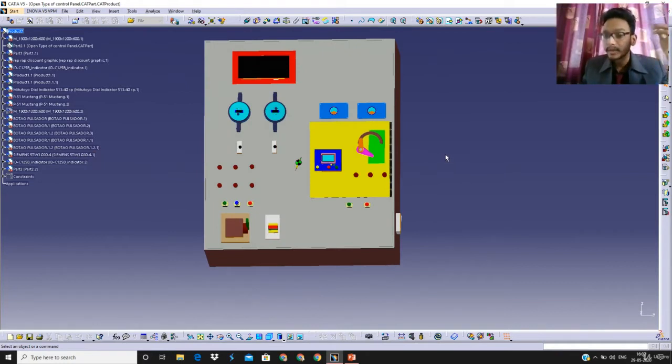And at the left side you can see there is a starter of a 3-phase induction motor. Before going to deal with this procedure, you have to use these contactors 1 2 3 4 5 6. So we are using 6 contactors to deal with either star connection or delta connection. In the case of star connection, you have to connect all these components like this, as I'm showing with the cursor, and there will be R, Y, B connected together along with a neutral connected to the motor. Or you can also go for a delta connection like this, and then there is no neutral needed in the delta connection, and you start the 3-phase induction motor.